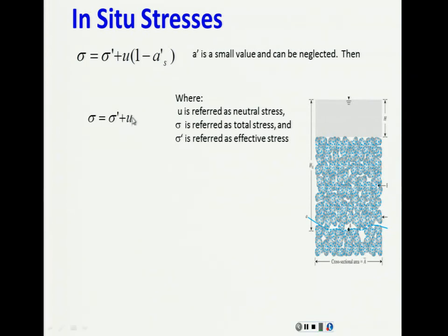And the pore water pressure is the same thing, so it's the pressure of the water also at that particular point. So we can derive from here the effective stress. And the effective stress is the important one. This is the one that affects everything in the soil. And you will say, why? Because this effective stress here is